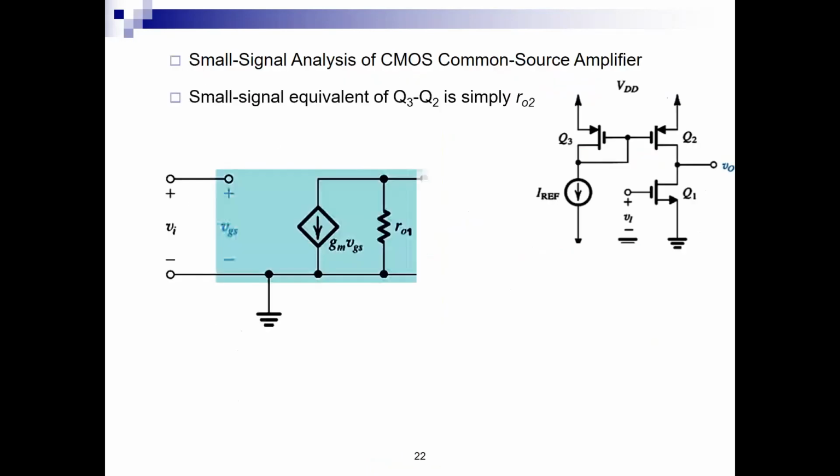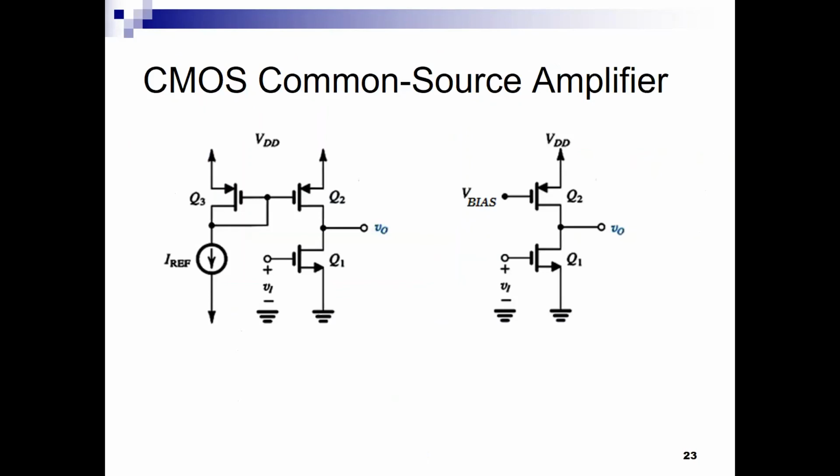Let us go back here. Look at this circuit that we just saw with the V bias. This transistor here has the gate at DC, the source node at DC, and I'm trying to see what I see if I look into its drain. In small signal analysis, I see an effective resistance equal to what? RO2. Okay, so these are rules. I will show you the resistor sheet next time. These are rules that we will start to look at.